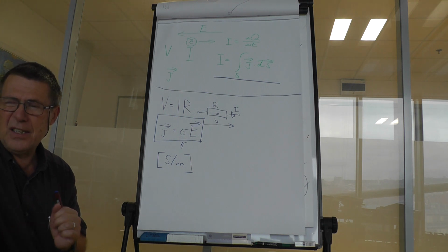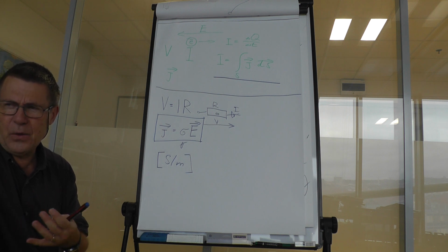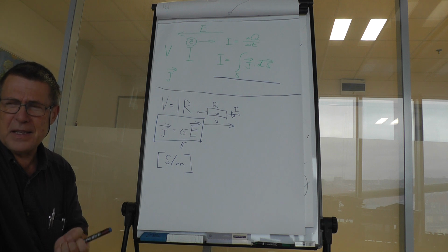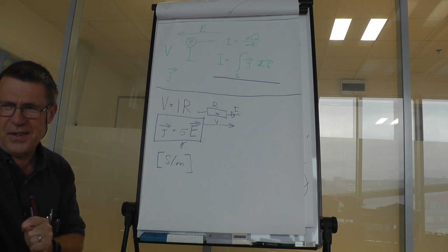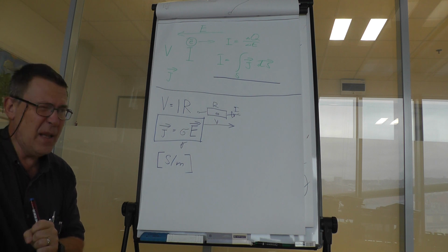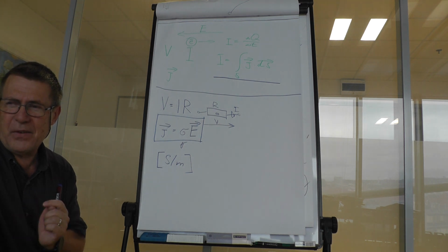So there is a discharge on the surface of the line, but you are walking under it and you can easily know that the current is not flowing through you. So there is some discharge that happens only around the conductor. Because there is high voltage on it, and because the field strength around the conductor is very big.